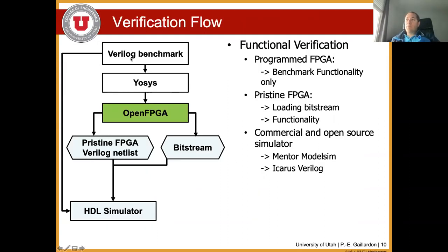We rely on a benchmarking effort where we take some benchmarks and run them through OpenFPGA. OpenFPGA generates your FPGA fabric, the one you're going to tape out, and at the same time, the bit stream. And so we have a way to merge them together inside of an HDL simulator to make sure that the fabric you are manufacturing, along with the bit stream generated by the tool, do actually match the initial benchmark you wanted to implement. And we do that for a very large number of benchmarks covering many test cases, so as to guarantee a decent enough coverage.